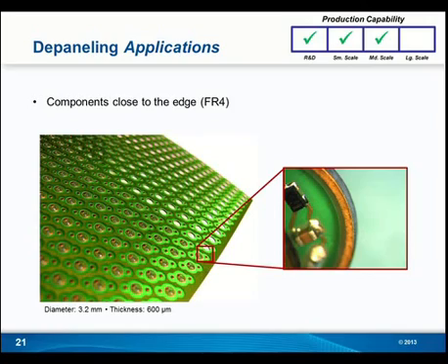With at least our UV lasers, especially the one for production, you have several options in terms of fiducials. You can read global fiducials. So if you have a panel that has maybe 6 parts on it, they're larger, and you're okay with reading 4 fiducials that are on the panel itself and then cutting everything else out, great.